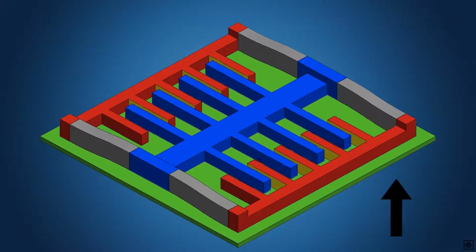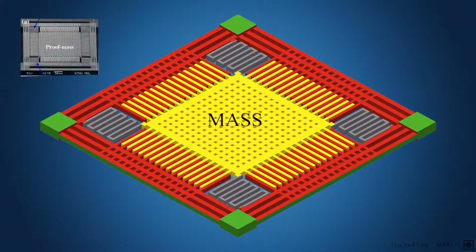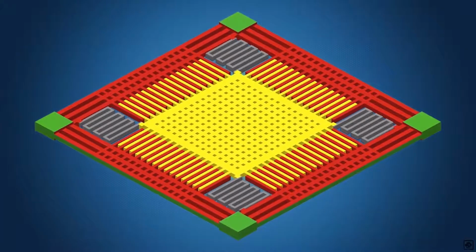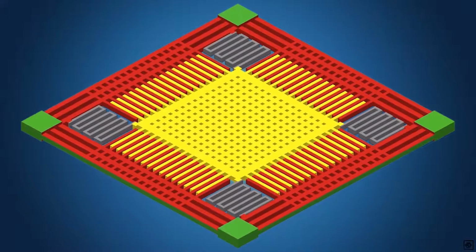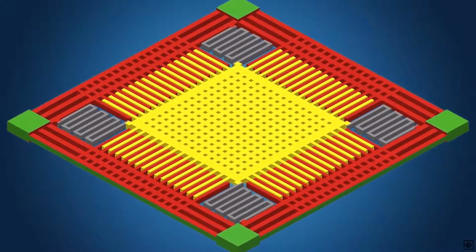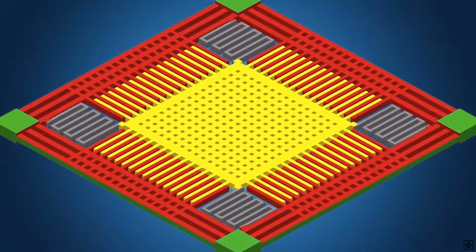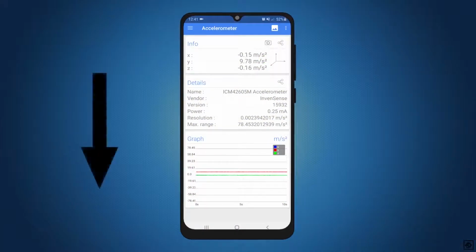This accelerometer can be modified to sense motion in all three axes. In this configuration, the proof mass is suspended in the center of the frame with the help of microscopic springs. Acceleration in the XY plane is sensed by capacitive fingers fixed on the frame of each respective axis. Both sensing structures also contain electrodes that can sense vertical travel of the proof mass, forming the simultaneous action of the Z-axis accelerometer. Now we can sense which way is down precisely.